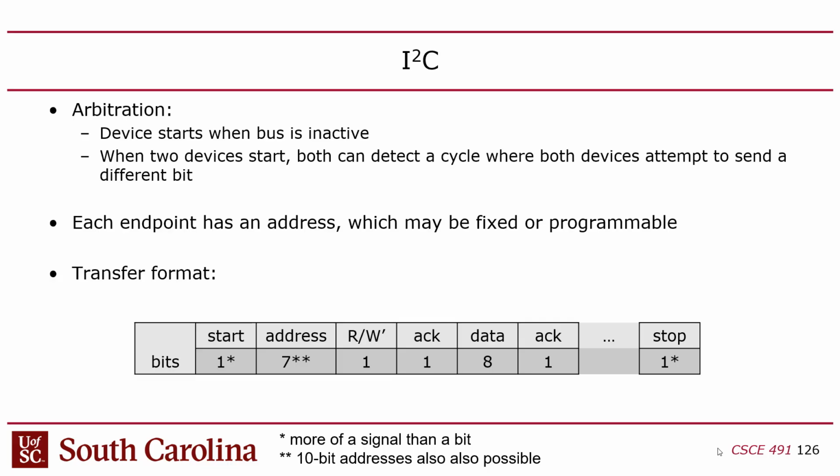Well, it could happen because there's no one listening. I might put a request out there on the bus, and whatever slave I'm targeting just isn't there, or is offline, or powered down. At which point I'll know, because I won't get an acknowledgement, in which case I'm like, all right, well, it's worth a try. I'm done with this. And you can bail out before you even finish the transaction. Make sense? Okay, so that's the idea.